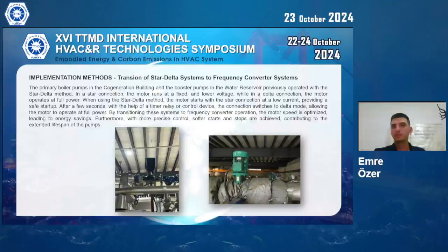When we do this transition to frequency converter systems, we can control these motors separately. And with frequency converter operation, the motor's speed is optimized, leading to energy savings. Furthermore, more precise control and extended lifespan can be obtained this way.